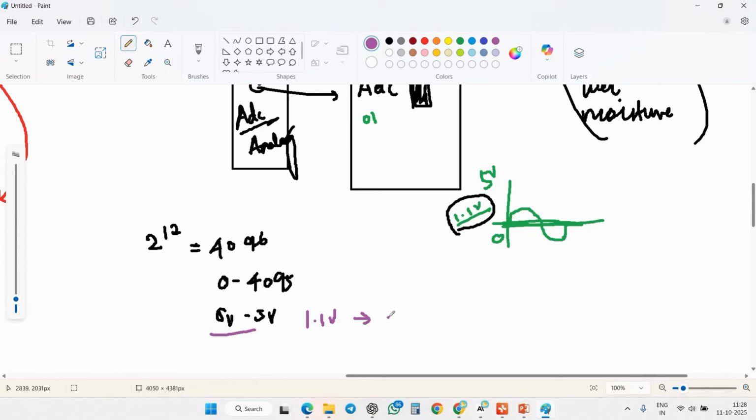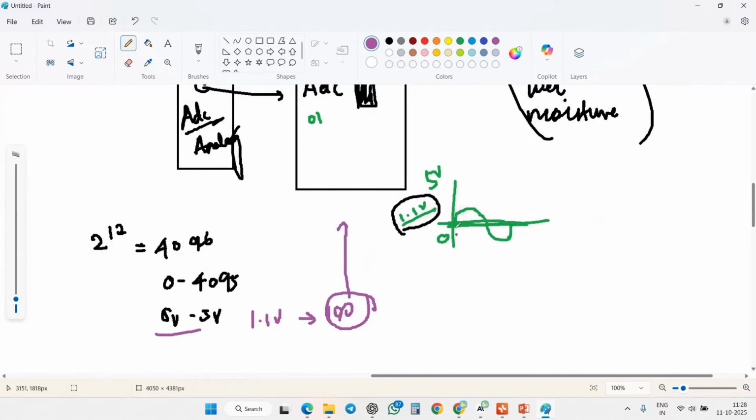It simply takes a value of about 100. It tries to match this value, because only those ranges can be understood by your microcontroller. It can't understand 1 volt, 5 volt and so on. So this time I'm converting these values into binary values, mapping your data.